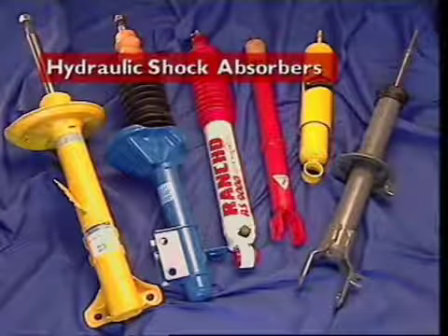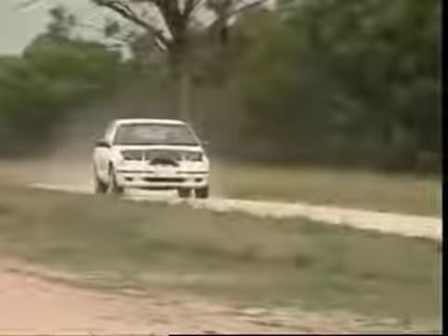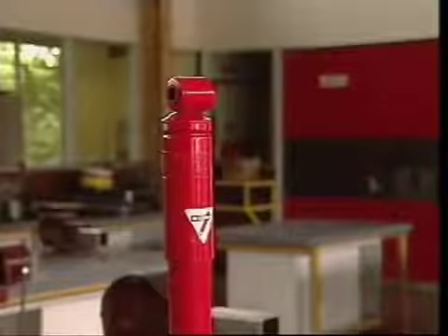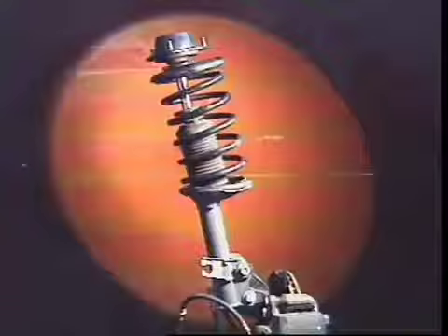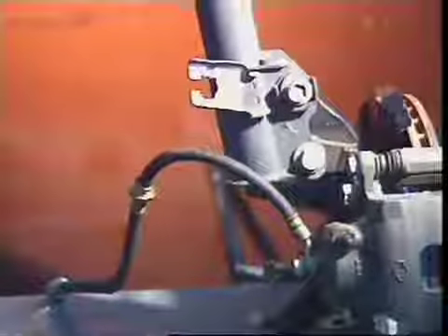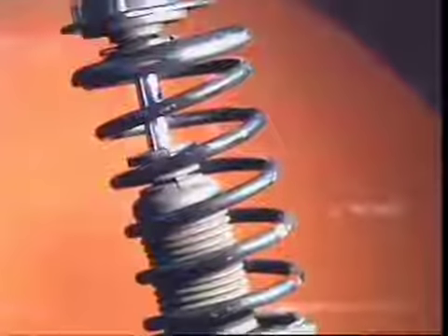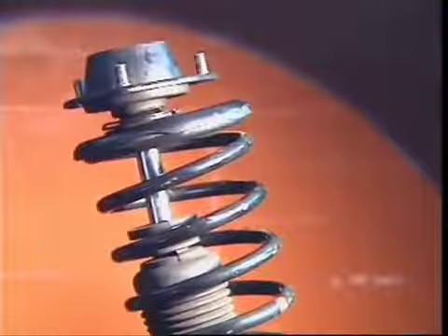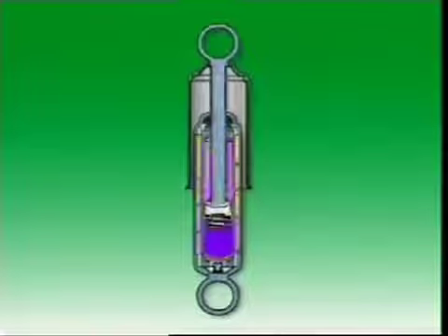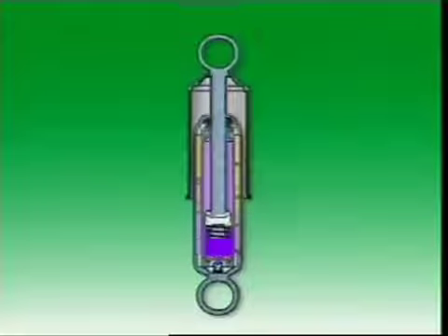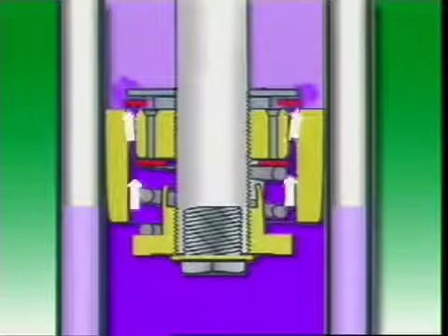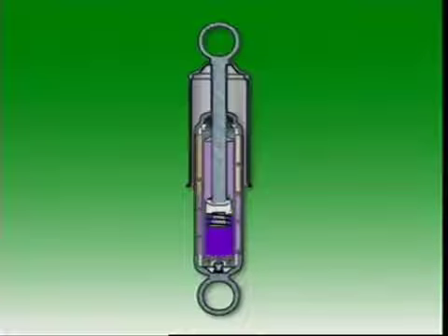This section examines hydraulic shock absorbers. The most widely used hydraulic shock absorber is the direct-acting telescopic type. It can be fitted as a self-contained unit or combined with a suspension strut. The strut type uses the same principle of operation but is considerably larger. The hydraulic shock absorber provides its dampening action by transferring oil under pressure through valves which restrict the oil flow. The twin tube type is the most common.